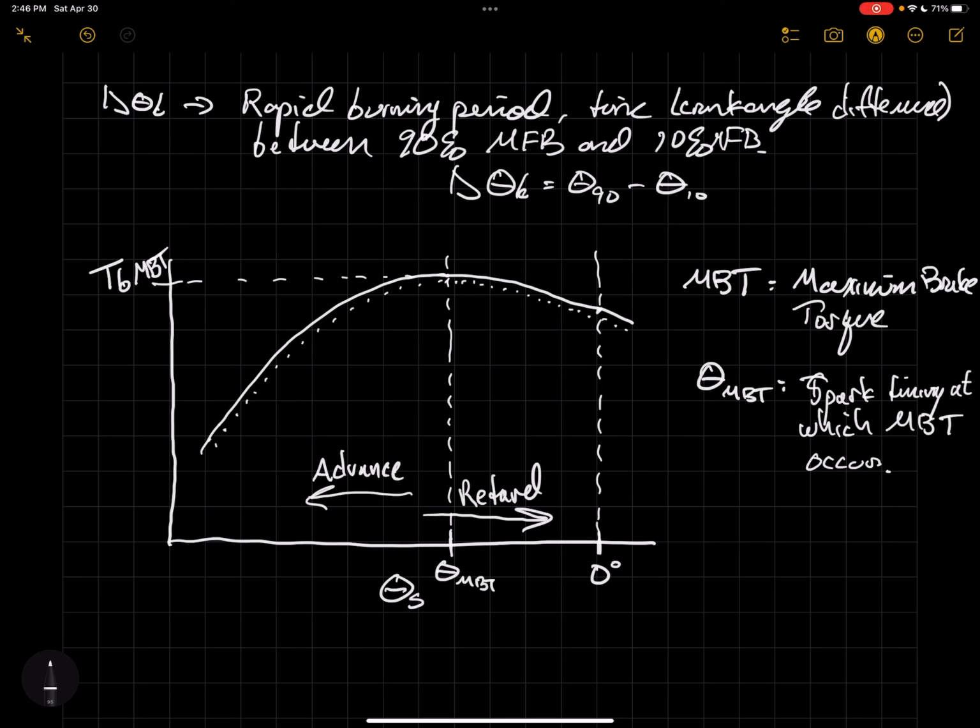And so the reason we have low torque for spark timings advanced of MBT timing is, first and foremost, something we call an "expansion" loss, okay? I'm putting expansion in quotes here because this is oftentimes a point of confusion for a lot of folks, but I'll explain during our next lecture how we have an expansion loss on this side of MBT timing. The other reason we have low torque when we're advanced of MBT timing is increased heat loss. And again, I'll talk about what that increased heat loss means in lecture number 40, okay?